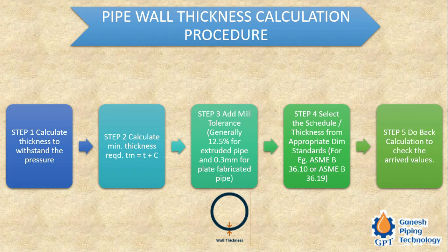Okay. The bottom line of this is that whenever we design a piping system, at the highest design temperature, if the pressure crosses the design pressure, then there is something called a safety valve. But suppose the safety valve fails, then what will happen? Will the pipe fail? No, the pipe will not fail, because the next level of failure will take place at the flange, because the flange is considered to be weaker than the pipe.